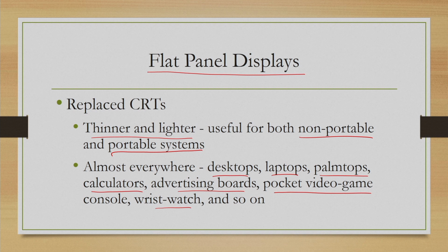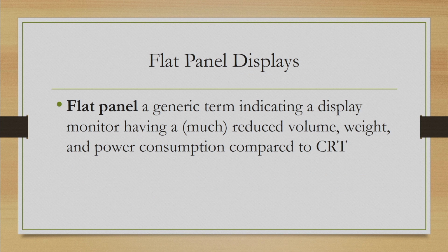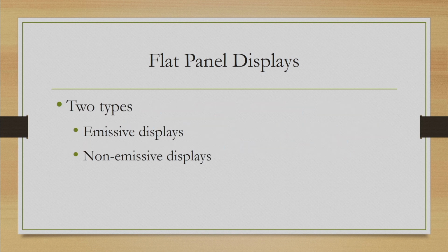Now, there is a wide variation in these displays. Flat panel effectively is a generic term which indicates a display monitor having much reduced volume, weight and power consumption compared to CRT. So, whenever we are talking of flat, it has to be understood in the context of a CRT. Now, there are broadly two types of flat panel displays. One is emissive displays, the other one is non-emissive displays.